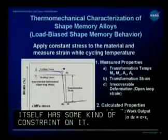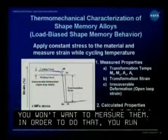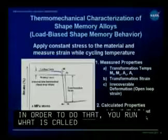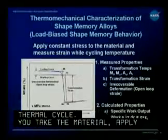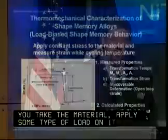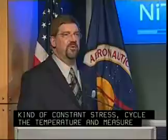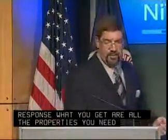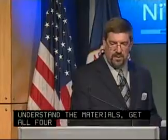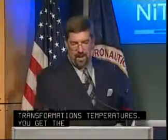So in order to do that, you run what's called a load-biased thermal cycle. You'll take the material, apply some type of load on it or some type of a constant stress, cycle the temperature and measure strain. And from that strain temperature response, what you'll get are almost all the properties that you need to understand these materials. You get all four characteristic transformation temperatures. You get the transformation strain, which is one of the most important factors here.